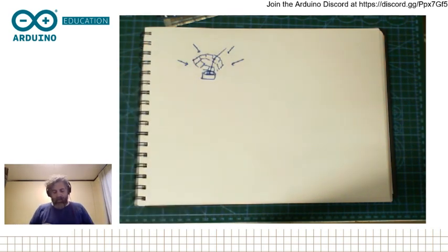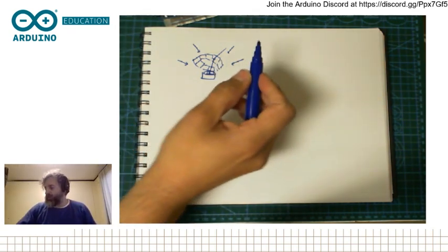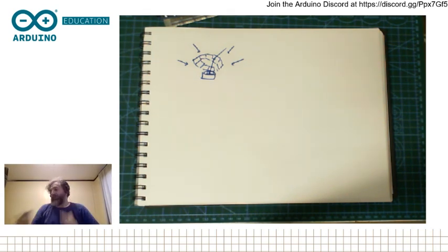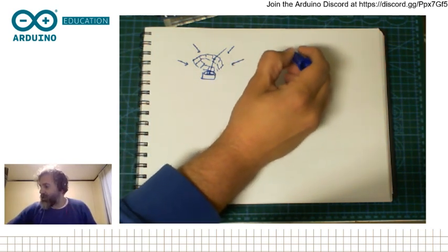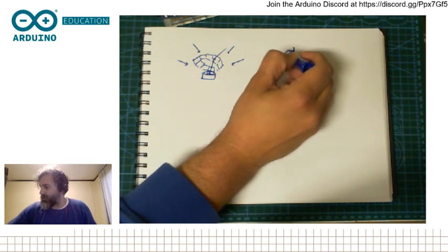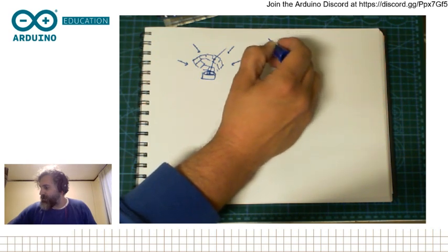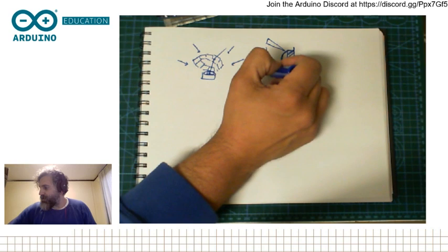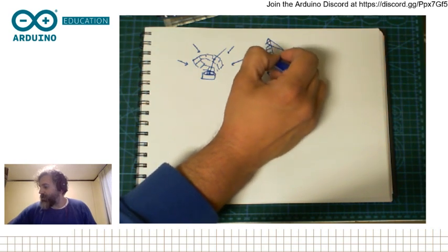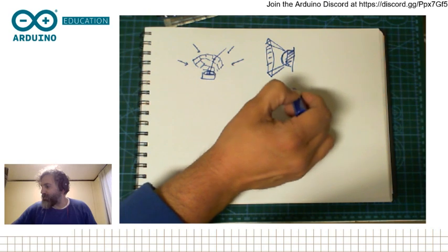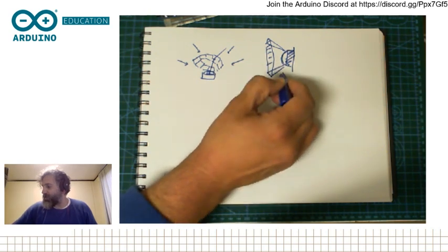That makes it very useful, because if you wanted to make a sensor that, instead of detecting omnidirectionally, 180 degrees or 360 degrees around it, just detects like a line, you could cover the cap of the sensor with tape or paint it black, so that it will only show an area of a certain width, and it will only cover that area, but it will not cover the full extent of the sensor, which is more like this.